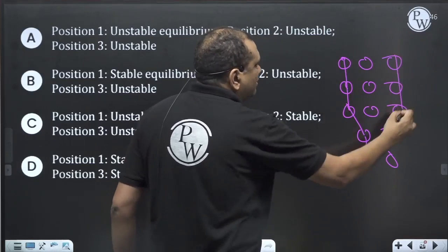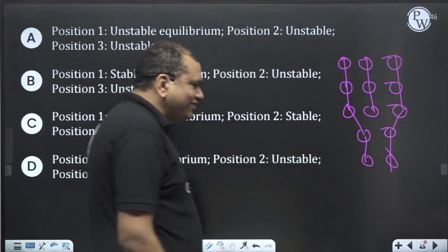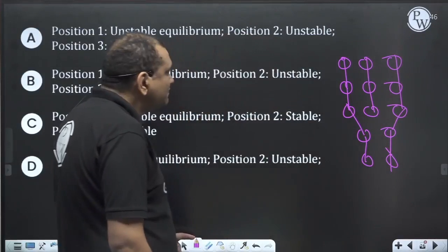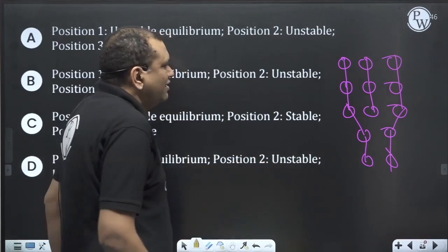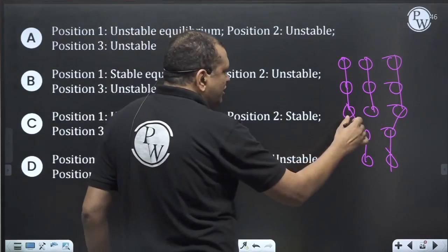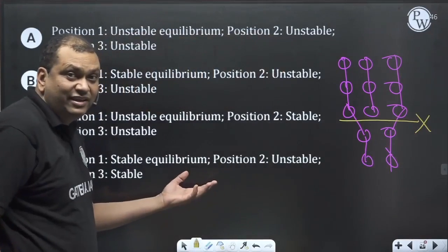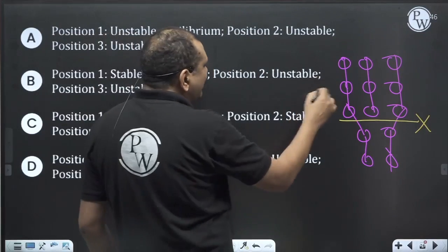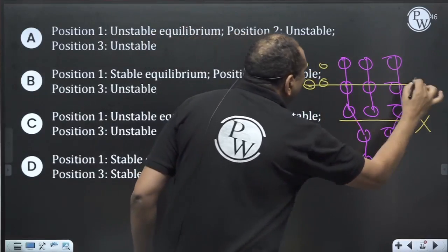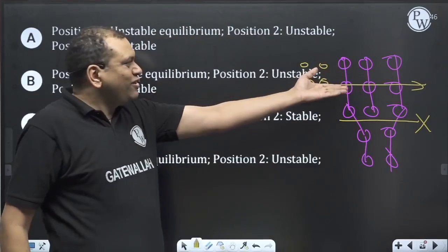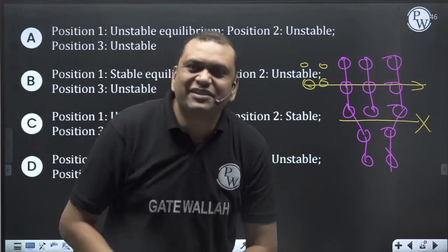Dislocation looks like this. Now this dislocation is locked and cannot move in this direction, X and Y. But suppose another dislocation is coming from here. From here the dislocation will be easily able to move because there is no obstruction. Interaction between the two dislocations is repulsive in nature.